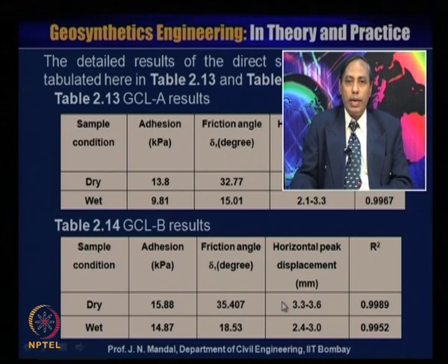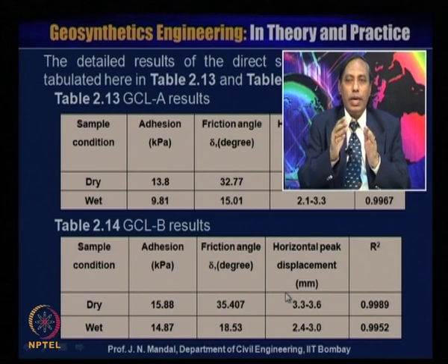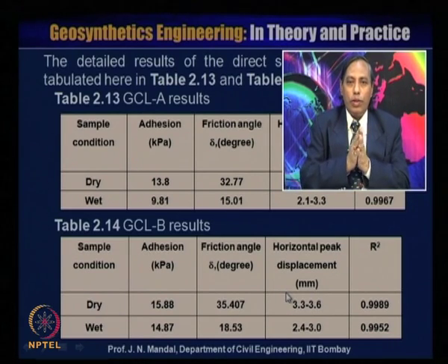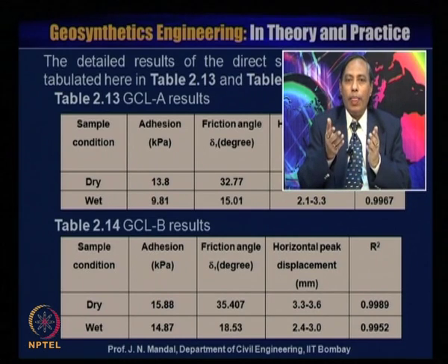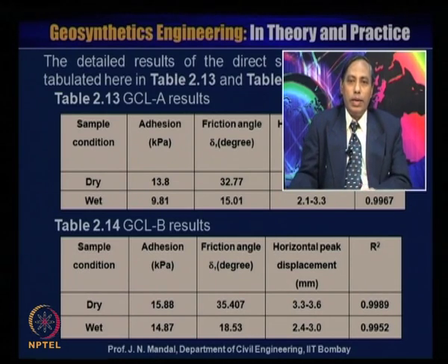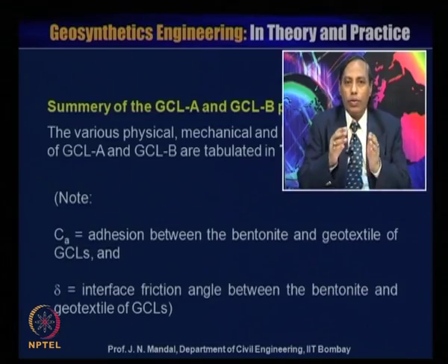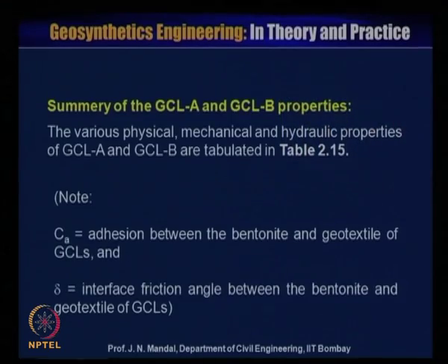So, in all cases, whether the geosynthetic clay liner is in the dry condition or the wet condition, in most cases the adhesion value is higher with respect to the wet condition. Both the adhesion and the friction angle are higher, but the horizontal peak displacement is not significantly different.